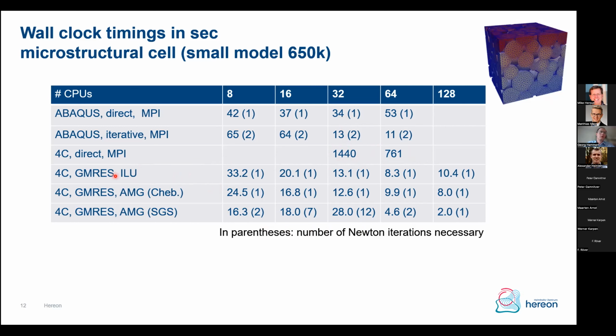So here, it's this version with the ILU preconditioning, fill level 2. You can see always 1 Newton iteration, so this is very good. It's actually, to be honest, a linear elastic problem. It's just about the 2 materials that are included. So it is fair to assume that it converges very, very fast. And also the prescribed displacement is rather small compared to the geometry. So this is in good agreement with what we expect.